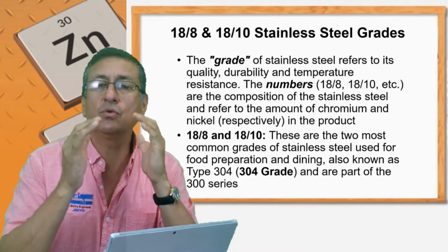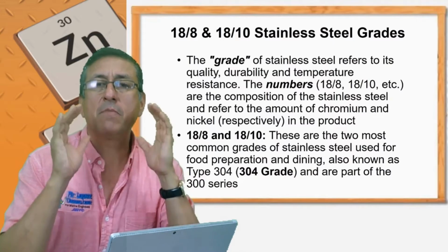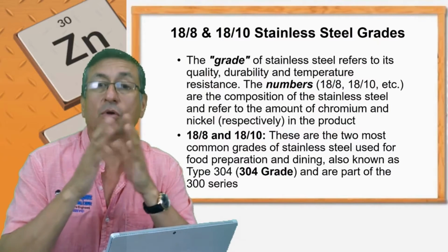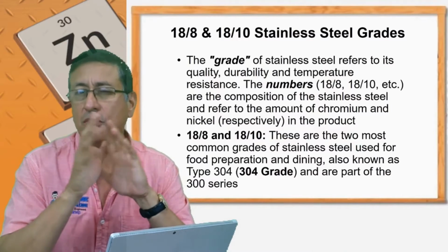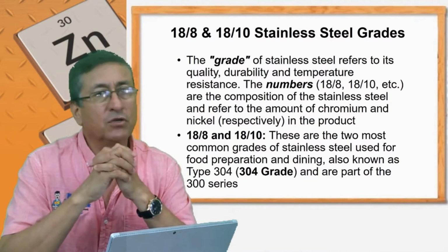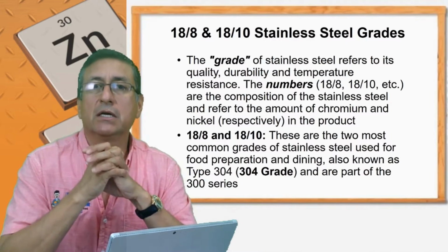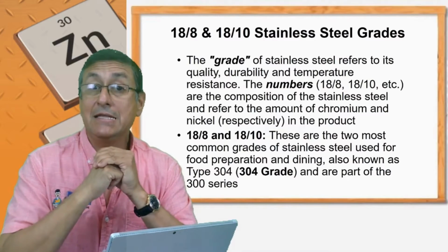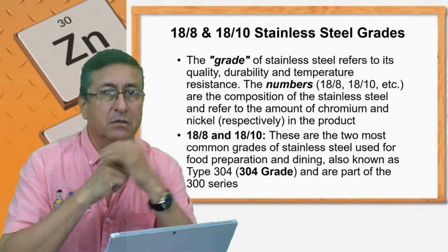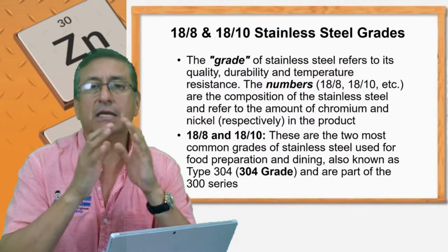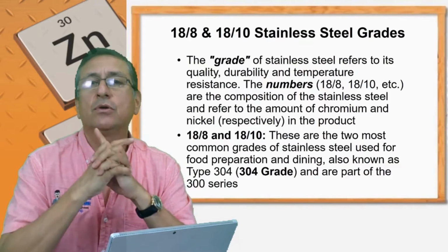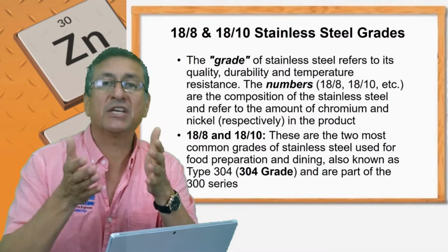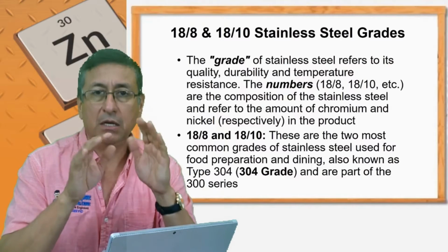Remember, we need to use only marine grade bolts, marine grade screws. Those are series 300. You remember 304 or 316, the most common marine grade materials. You remember the type 18-10 and 18-8. You remember that slide? This is critical. You need to keep in mind: always use marine grade hardware for bolts, for screws, for washers. All of them should be marine grade.